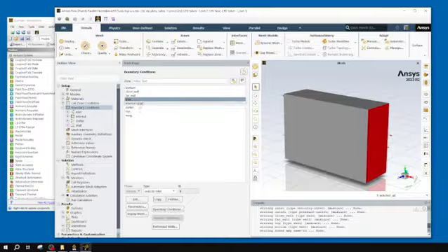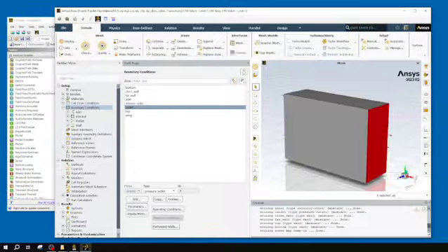So for my outlet, I'm going to use a pressure outlet. You have a couple different options here. The other most common outlet type is going to be a mass flow outlet, but again, it's very dependent on the case. If you're using different cases, you can change out what you want. Outflow vent or an outflow outlet vent. But most common you see is actually this pressure outlet. So I'm going to leave that here.